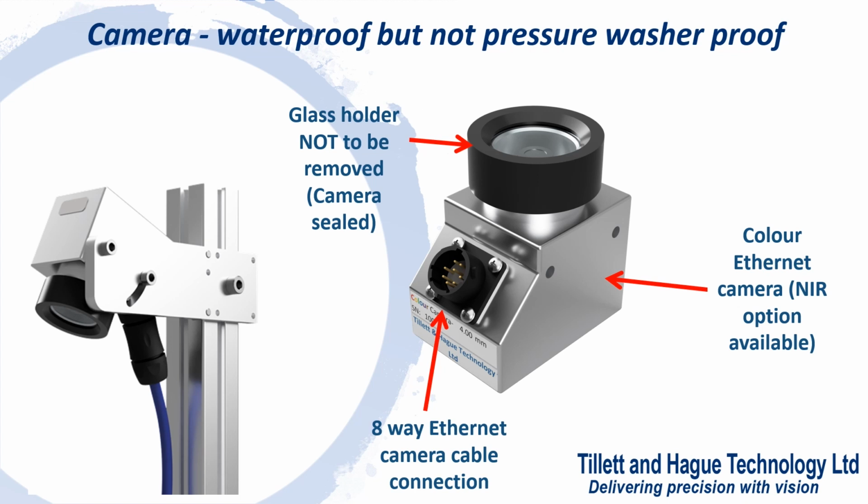We offer our cameras with 2 lens options, 6mm as standard for normal inter-row applications, and a wider angle 4mm lens for special applications, where the camera cannot be mounted sufficiently high to get the required field of view. The lens type is shown on the label, but lens data is programmed into the camera so that it can be automatically recognised by our system and the correct parameters used.